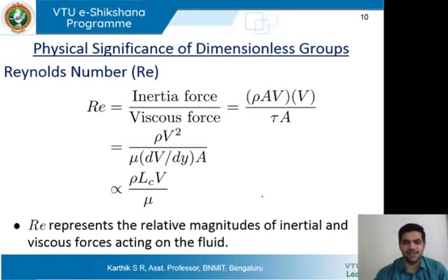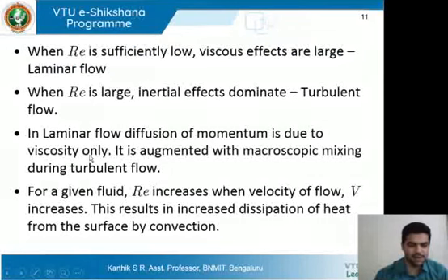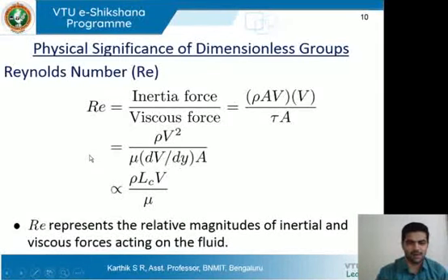So if you have a surface and a fluid is moving on it, you are familiar with the no slip boundary condition. The fluid that is adjacent to the wall will have zero velocity, which exerts a resistance to the layers of the fluid above it. Which will result in a propagation of momentum disturbance in the y direction.